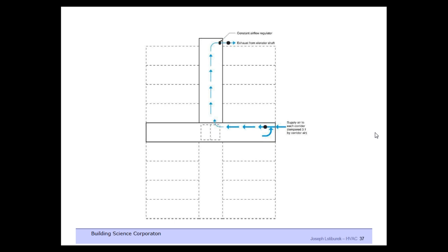It's nice to have the elevator under a slight negative pressure. You're going to need to provide some form of makeup air, and that makeup air is going to be typically introduced into the corridors. And this air is generally not going to be conditioned, and it really doesn't have to be because the flow rates are exceptionally low. We're talking maybe 15 or 20 CFM per one of these long corridors. And what's nice about that is you can just simply use dilution mixing of the air in the space to partially temper this air.